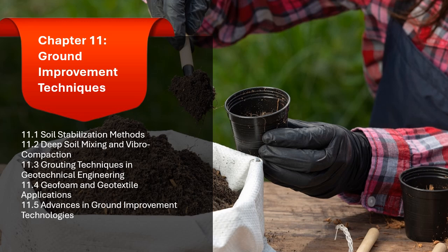Once the compaction process is complete, the vibraflot is removed, and the ground is left with improved density and stability. In some cases, densification may be verified by measuring the soil's relative compaction or by conducting field tests, such as the Standard Penetration Test, SPT, or Cone Penetration Test, CPT.